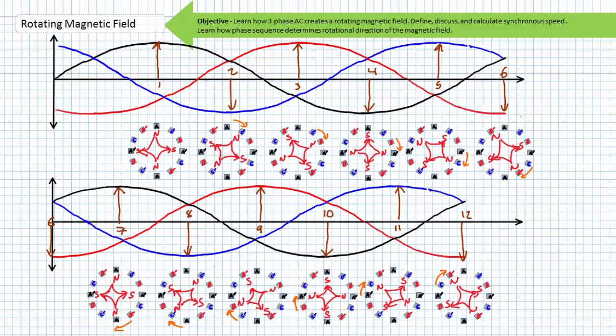So my earlier shortcut where one pole pair dominates a portion of rotation is an obvious fallacy, but if you don't care about all the nitpicky details, it essentially yields the same results. The take-home point is for a 2-pole pair per phase stator, the magnetic field does a half turn for a single cycle of an AC waveform and completes a full revolution every 2 cycles.